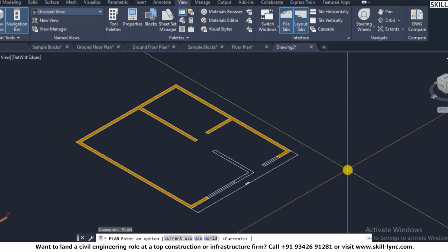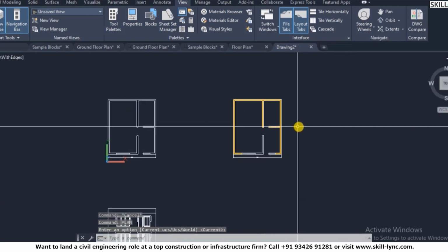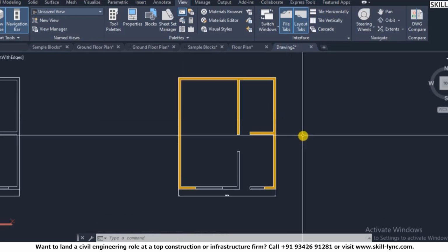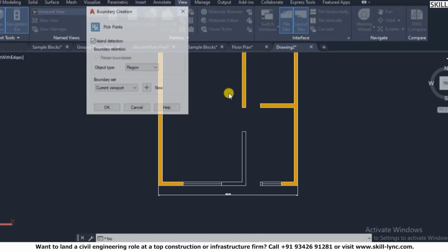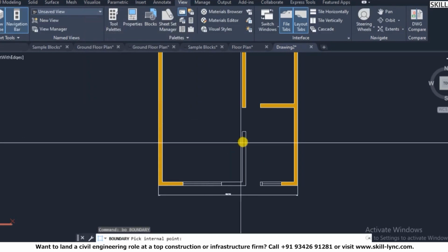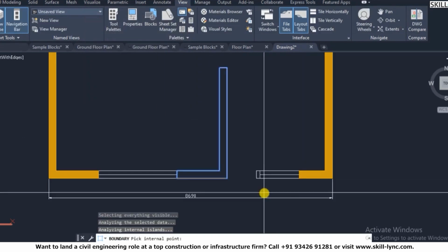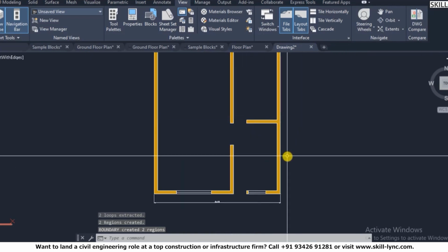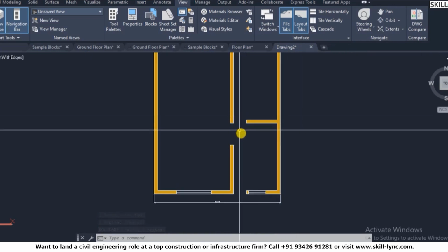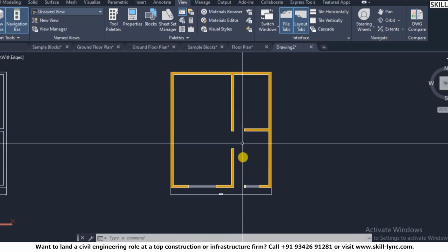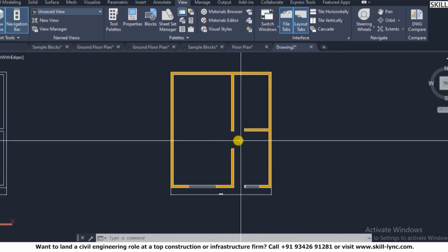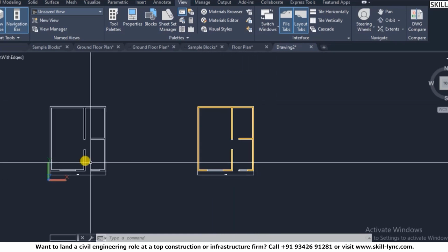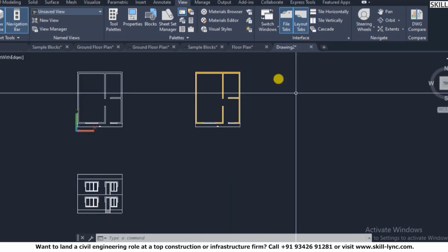So now I can see that here the plan option creates the plan view that is parallel to the UCS. So this is the UCS. Now again I need to go for a pick point and create the walls. So this is something that I created, and here I have two doors to this particular space. You have this door here, and this is another door that would be going to this passage. So there are three rooms over here in this particular building that we are going to make.